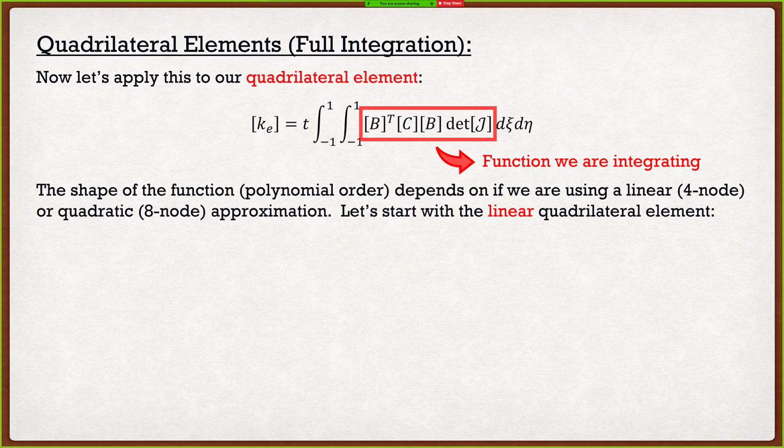No one wants to take a shot in the dark? I got one that's saying that it could be a 5th order polynomial. Well, if you do the math, and again, this isn't a question you should have known, the only way you can really see this is if you do the math and then look at the matrix. It's actually a 3rd order polynomial. The highest order that we'll have is eta and zeta cubed. So if this is going to be a cubic function that we're integrating, a cubic polynomial or 3rd order polynomial, how many integration points did we need for a 3rd order polynomial?